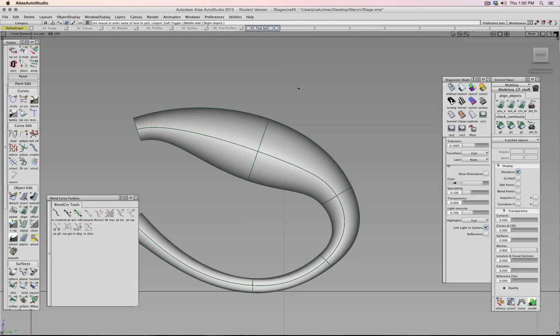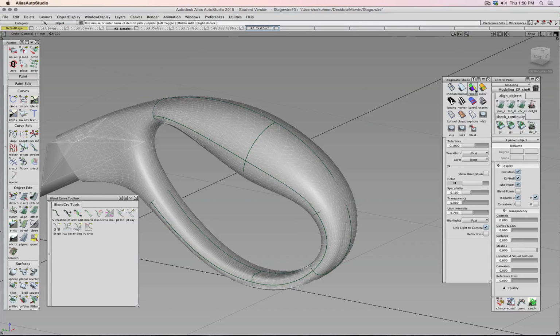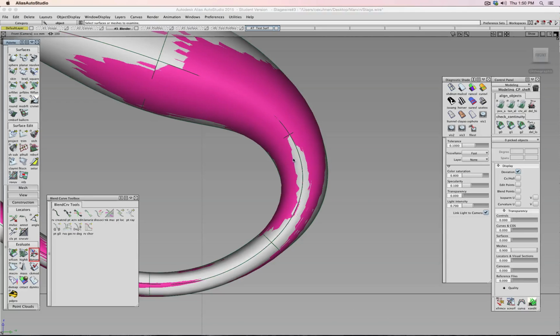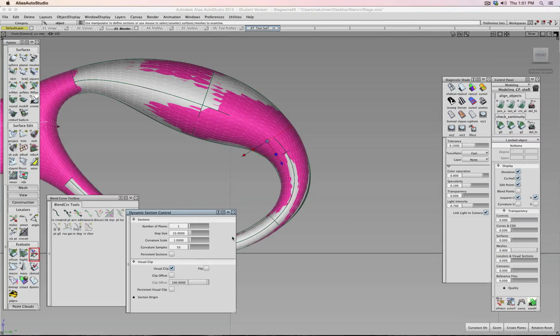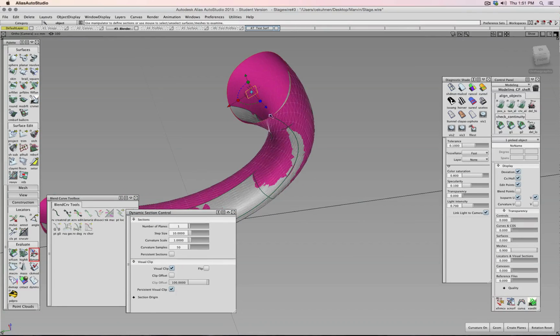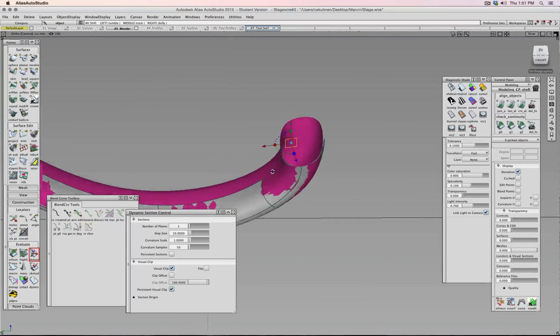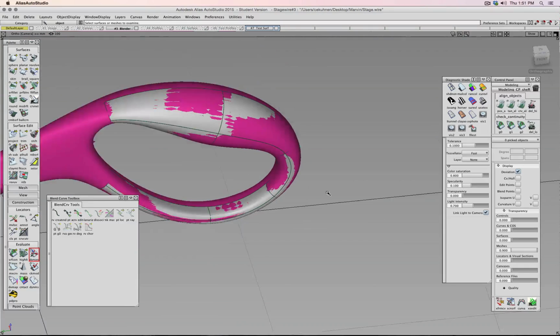Okay, so that was a quick rerun of how, for example, to change that shape. Let's still compare it to our Blender model. Let's see how we are doing. Let's select the Blender model, give it a different color, because I would like to see how we are doing with our curvature up there. And there and there. Okay. There we miss it a little bit. But actually, you see we're pretty spot on. Okay, so I think this is now really at the stage where we simply could leave it.